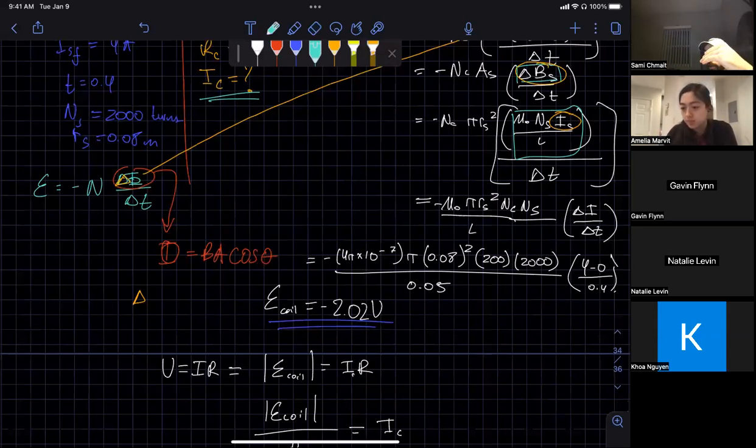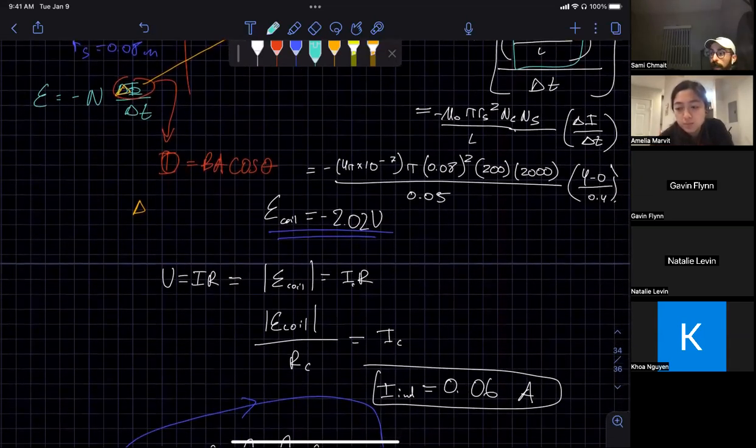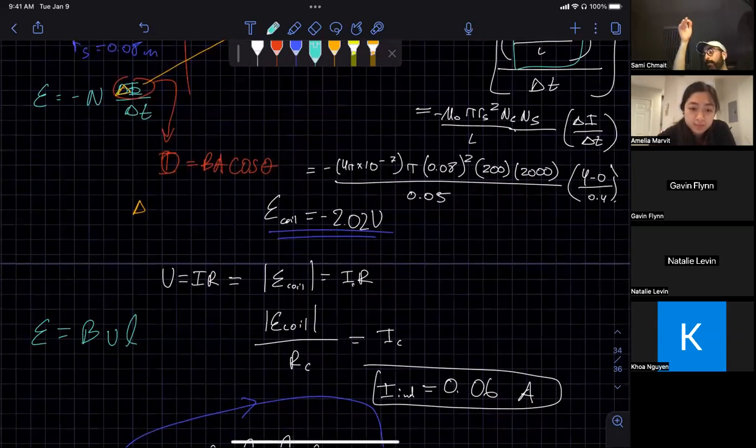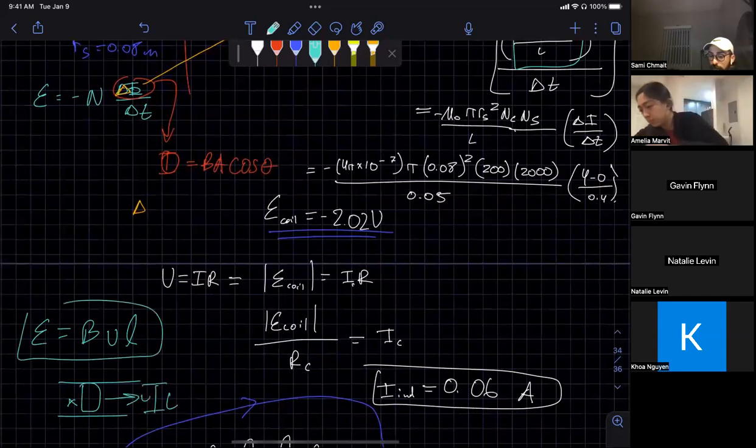If you see a rectangle or square, you can immediately solve for the induced EMF using the formula: induced EMF is going to be equal to the B field that's acting there, times the velocity at which it moves, times the length that's going to be moving up and down, right? So it'll be some situation where it's like this, where that's the field, and you're going to be moving like this, and this is going to be equal to L. Okay, so that's a special condition that you can use.